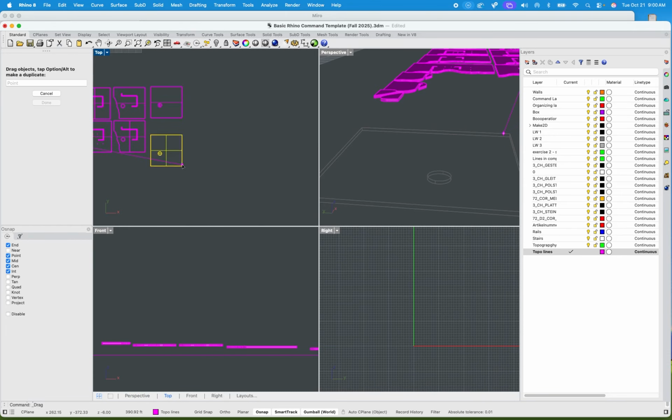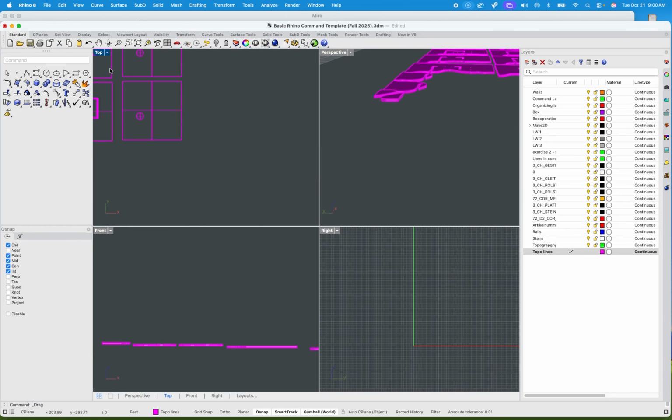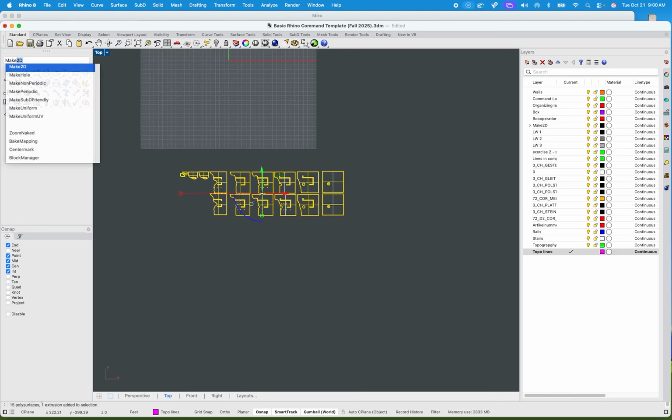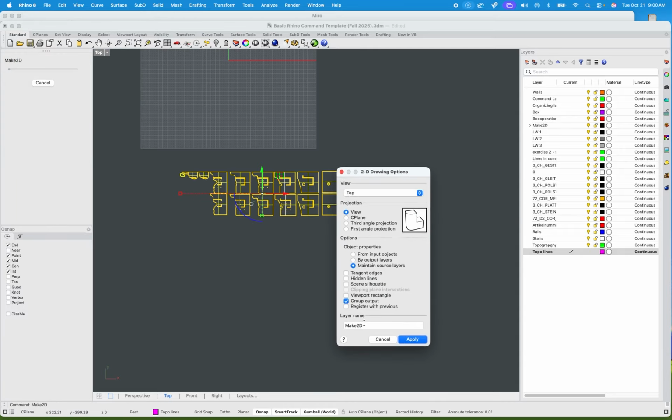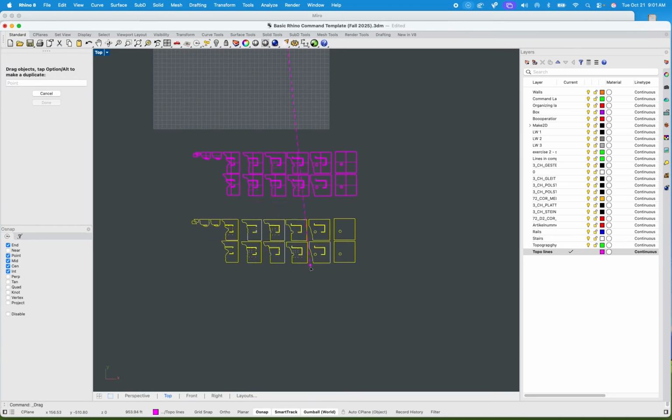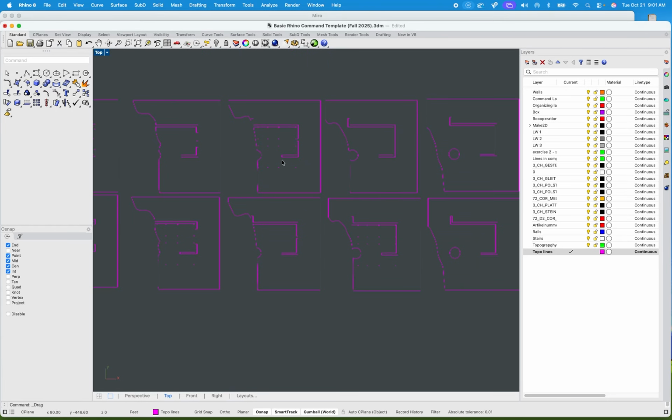But there's our bottom layer, and it gets the circle. But instead of doing this one at a time, it makes a lot of sense to line them all up first, take every piece, and make 2D. Back in the day when I was a student, I would have sat there and made 2D with each little piece, right? Not knowing that I could just do it all at once, make 2D, bam, there's all my laser cutting lines. Done, right? Down to the very T.